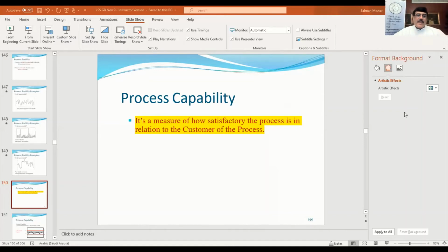Anyway, after you decided what data you want to collect, and you checked if there was any error in it, you checked the stability of it, and so on and so forth, now what you want to do is establish your baseline performance. What is my performance now? And this is called process capability analysis.